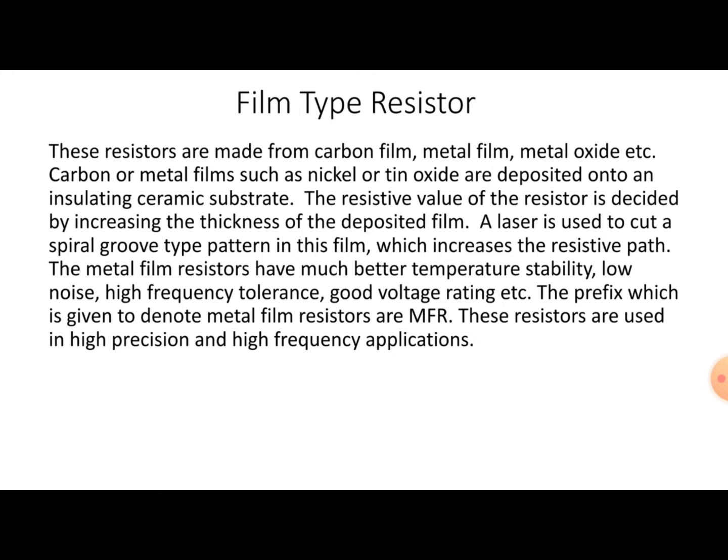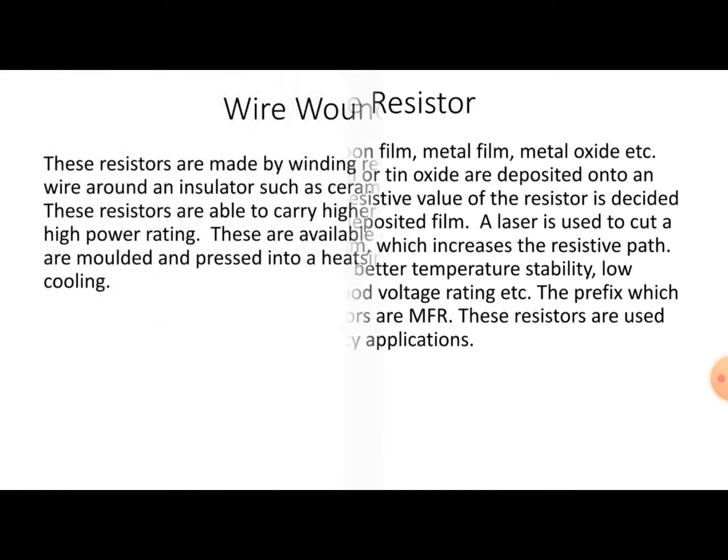The metal film resistors have much better temperature stability, low noise, high frequency tolerance, good voltage rating, etc. The prefix which is given to denote metal film resistors is MFR. These resistors are used in high precision and high frequency applications.